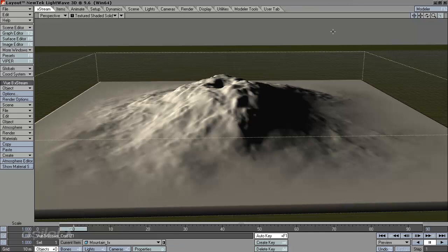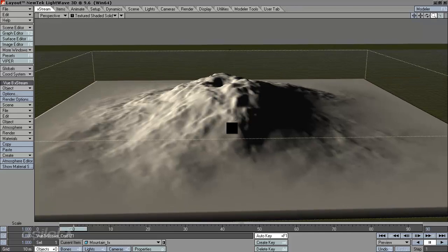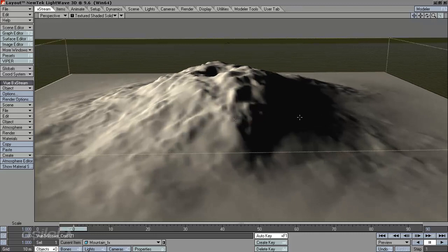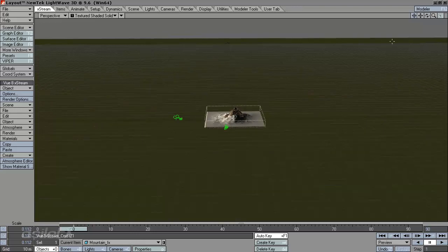There is the ability to save the actual proxy that we had instead of saving an object copy in order to maintain the scale and preserve the object within the scene. If you're going to do that, just select the proxy and save it and then open it in Modeler and modify it. You want to make sure that you have your view scene saved first, and I would really suggest making another copy of it, a duplicate copy, in case it gets corrupted. And then after you save the object, update it in layout or in Modeler, merging the points and keeping it in the scene, closing the view scene and reopening it. And that should potentially fix things. Not necessarily going to, but there are always a few things to watch out for.